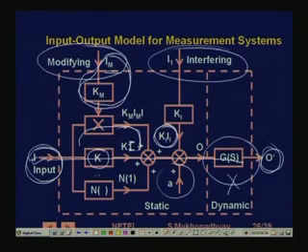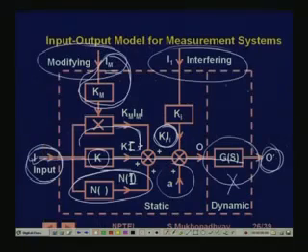In addition there can be some nonlinearity effect, this is NI. So for example, if you are going to make a very accurate measurement, then sometimes you put in those nonlinearity effects, and you can say that in this temperature range, in that temperature range, use such polynomials for temperature to resistance variation. People use that. So this will probably give you a much more accurate behavior of the instrument.